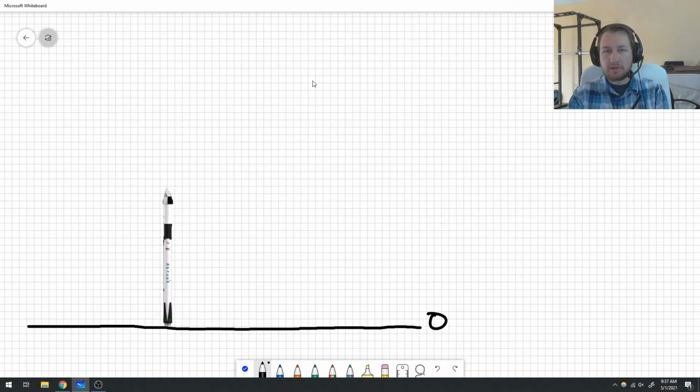But a Kalman filter is ultimately a way of combining multiple sources of information about your state, right? And so the simplest Kalman filter would be to still use a barometer, but you also use an equation. So this is what's sort of the predict step, right? You can sort of think of the prediction step as having another measurement sensor in there, right? But the measurement doesn't come from an actual real-world measurement.